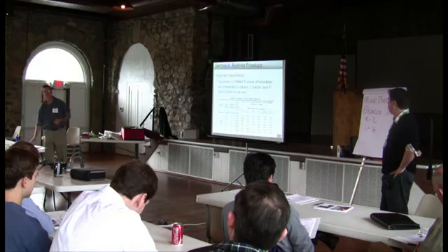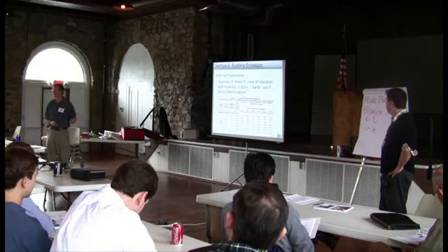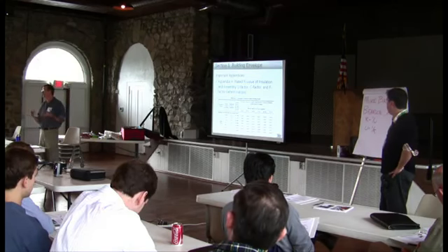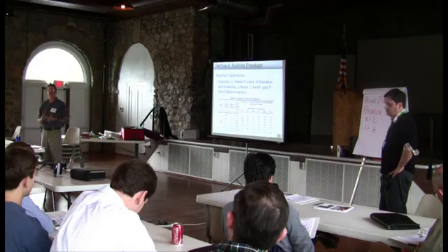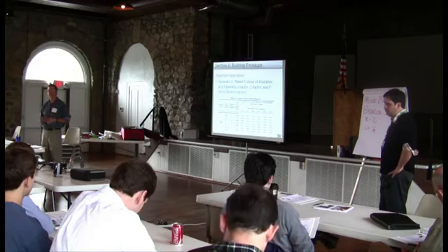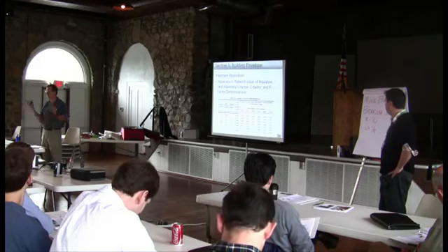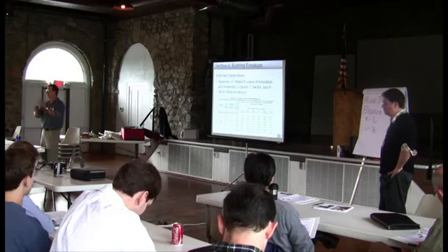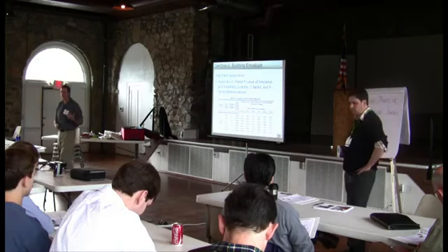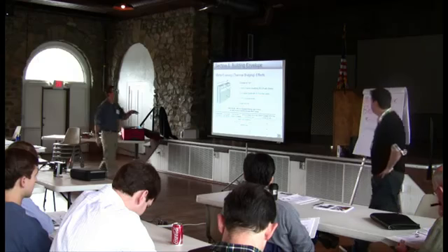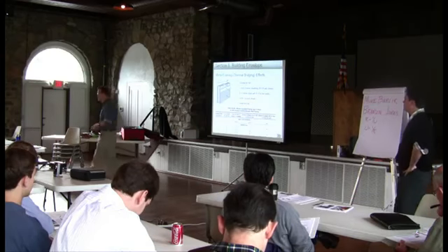Many of these tables are built into ComCheck as well. If you just describe to ComCheck what you're building, it will come up with a U factor for the assembly. So very rarely are you going to have to go back to the real air films and all this kind of calculation. Those are factored in the code, as is the effect of thermal bridging.